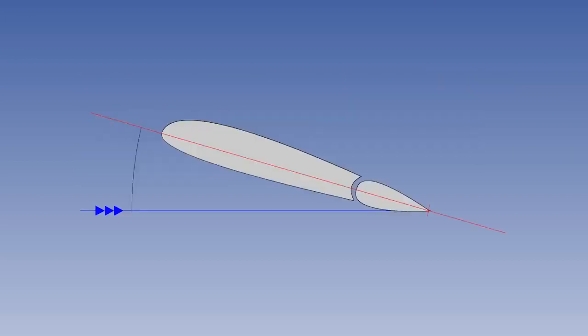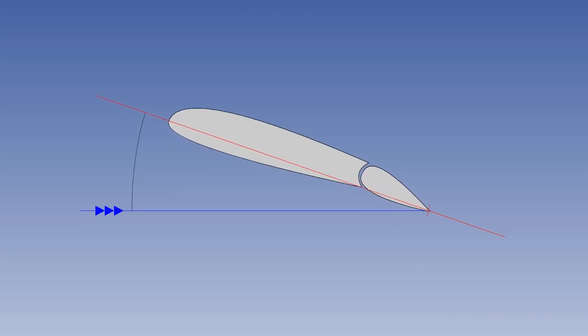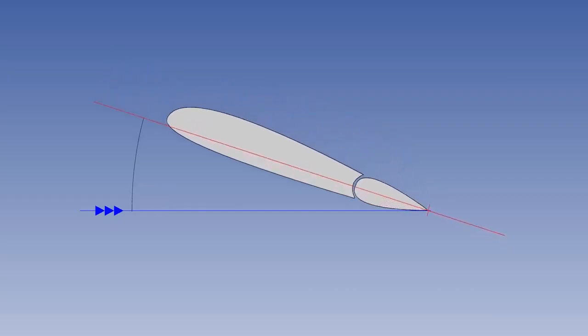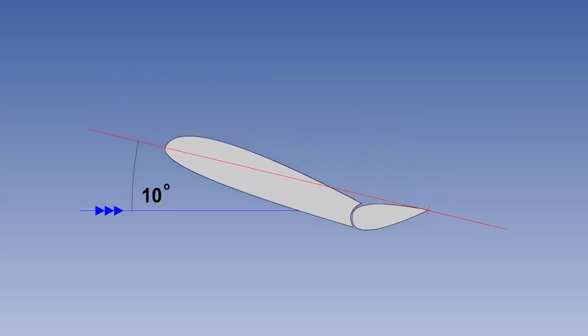Moving a control surface alters the chord line and hence the angle of attack. An aircraft may have one wing which is less efficient than the other and stalls slightly before it, causing a wing drop. Trying to lift a dropping wing with aileron will increase its angle of attack further, taking it deeper into the stall. At the same time, the upgoing aileron on the opposite wing will decrease its angle of attack, possibly unstalling that wing, which produces more lift and exacerbates the roll already made worse by the changes in effective angle of attack.